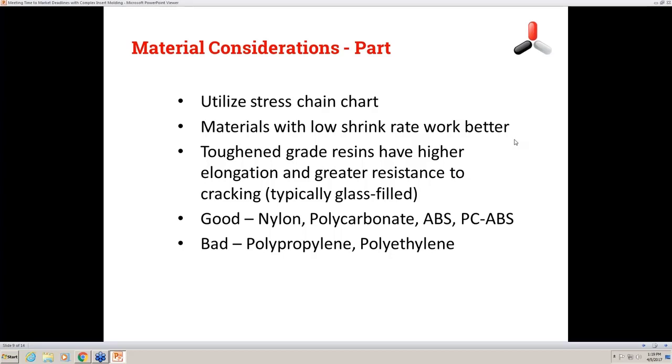It's a hard flow. So keep that in mind as well when you're looking at your custom insert molded. When we're flowing that material over top of it, that's a cold insert, whether it's metal or whatever other type of material. The more material you put over top of that insert, the longer it has to flow over a cold surface rather than a hot mold. So give it its wall thickness, make sure you're following those material guidelines, and make sure you're getting the right material to work with your part.